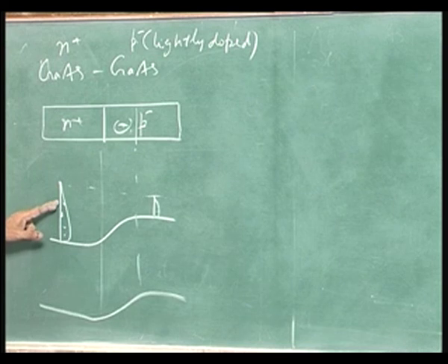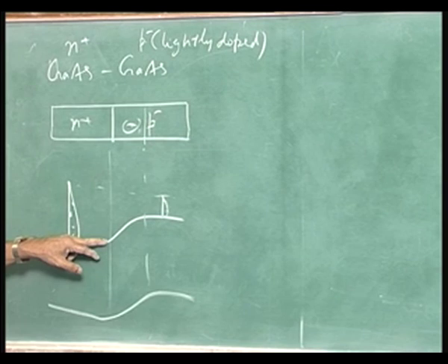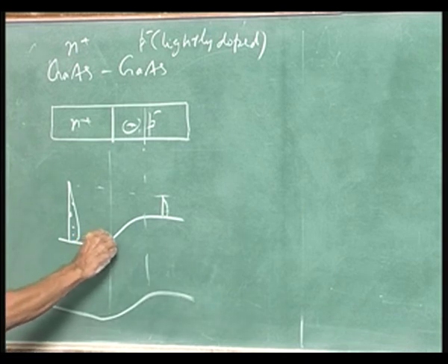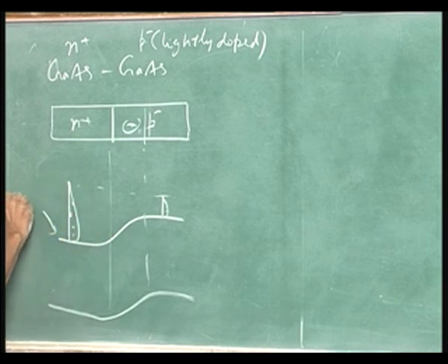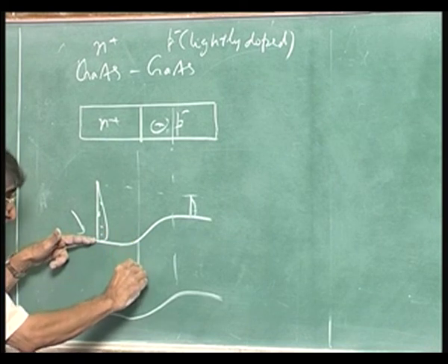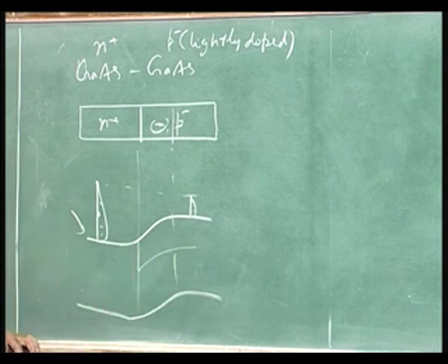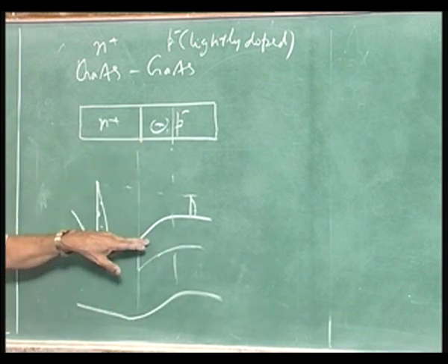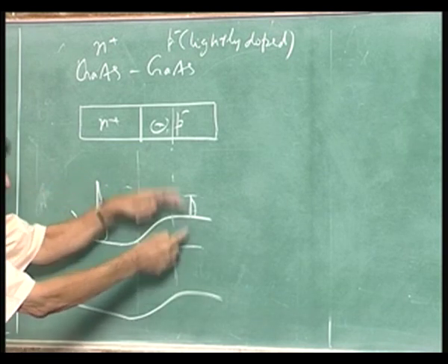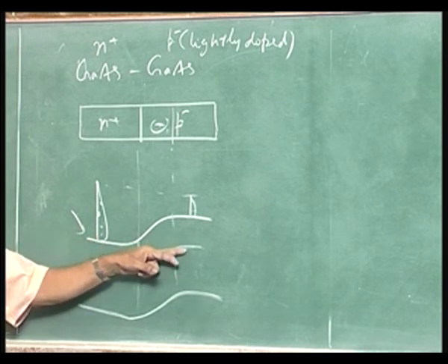Okay. Now, if you replace this gallium arsenide, what happens? There is a notch here, okay, and I just draw this, maybe I will continue on this next lecture, but just now, if it is aluminum gallium arsenide, okay, this is for gallium arsenide. I am drawing the conduction band the same way, let us not worry about that. What happens is, here it comes down like this. Then if it were the same built-in potential, how would it have gone? Like that. What happens if it is the same distribution? Same potential barrier as gallium arsenide, then this is at a higher level, thermal equilibrium, this is at a lower level, the whole thing is pushed down. Then there is more transfer of electrons from the aluminum gallium arsenide to gallium arsenide. If more transfer takes place, what happens to this? That will come there like that.